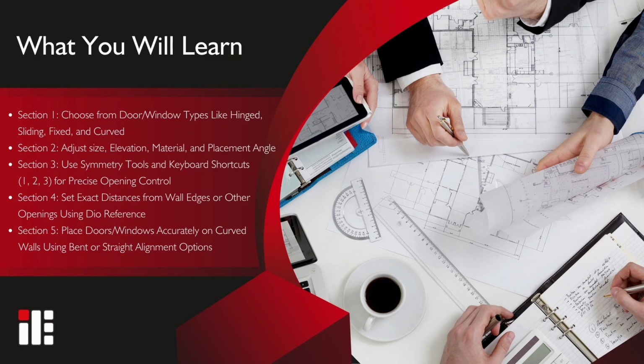In this video, you'll learn how to place and customize doors and windows in ideCAD architectural for accurate and detailed building layouts. We'll show you how to choose from various door and window types, adjust their size, elevation, angle, and materials, and control insertion settings like symmetry and opening direction.